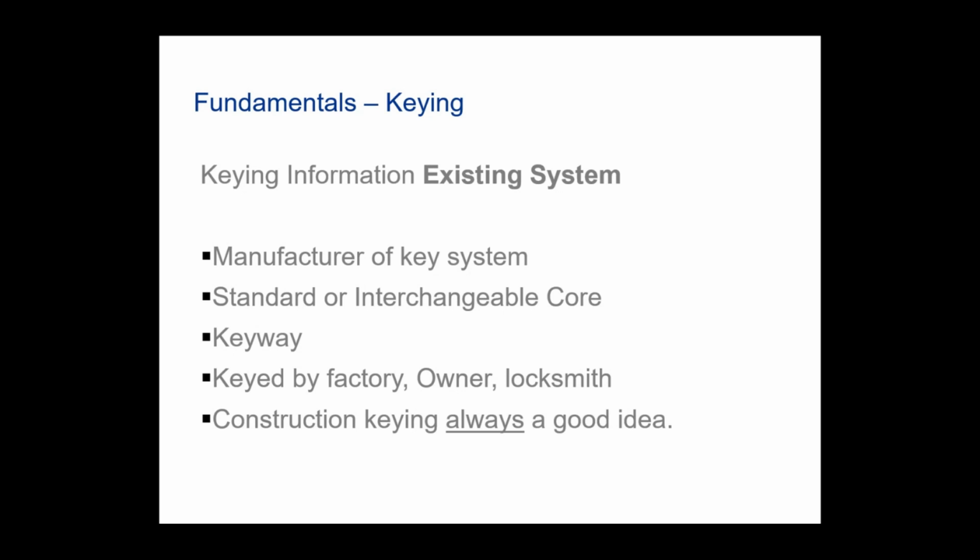You'll want to know in your existing system, is the factory going to key the new locks? Is the owner going to take care of the keying themselves, with their key shop in-house if they're at a university or a hospital or a government building? Or are they going to have a local locksmith that's worked with that end user in the past? Are they going to key the product? Make sure that you identify that, because that's a major issue, especially during the building process.